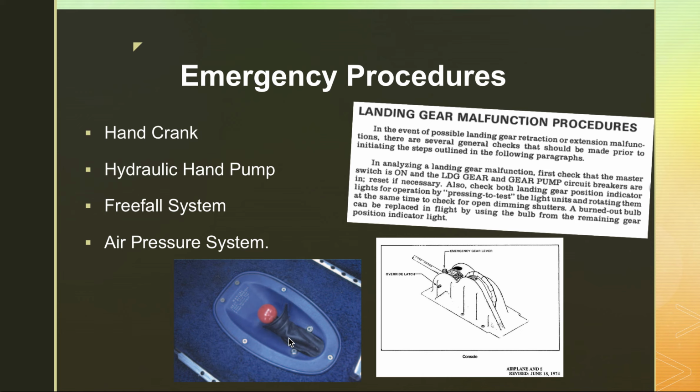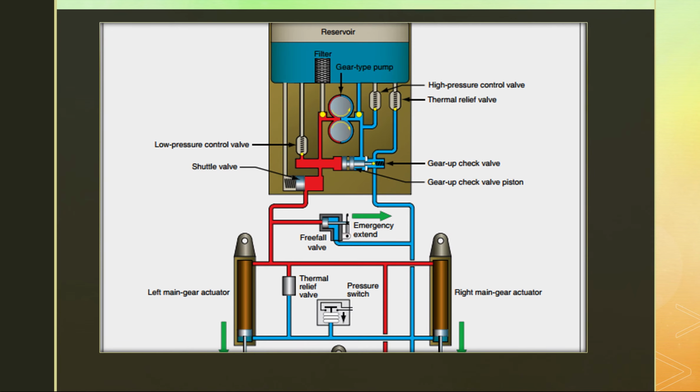The Cessna single piston gear extension system is going to be a single hydraulic pump here. So the Cessna system does need hydraulic fluid because those wheels have to come forward as they come down out of the fuselage into the airflow. To do that, you pull the handle forward, and then it's just a long pump handle at that point, like running the bottle jack of a tire jack or something like that. The other two we already talked about. The free fall system, again, that's how it works. You pull the free fall valve, and all it does is let the weight of the wheels push the fluid from one side of the piston to the other.